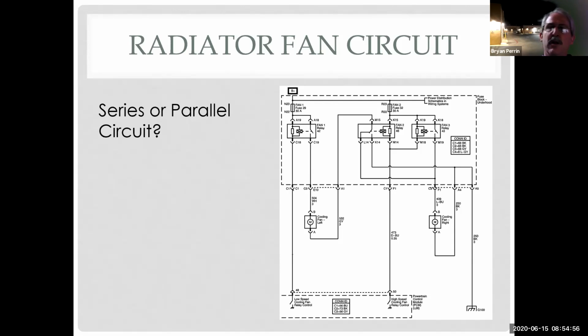So this is where cars will overheat or run too hot, maybe because one of the relays goes bad, or one of the fans goes bad. I can no longer make a low speed circuit. So now I'm either overheating or not overheating. I no longer can control it down at a normal operating temperature. And the computer turns the relays on.